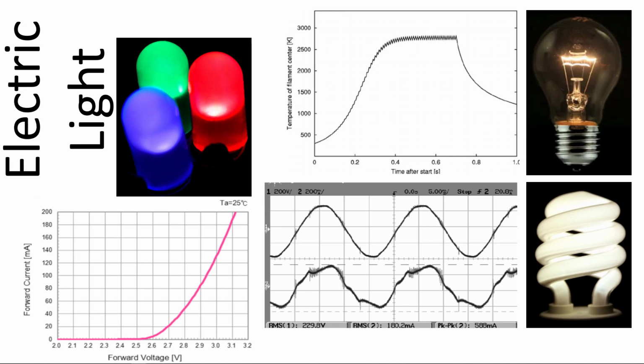LED lighting, and here I'm just showing a standard forward current with forward voltage. Notice that you have no real current until you hit about 2.4 or so volts. And as you steadily increase the voltage, you get steadily more current. With an LED, if you increase the luminosity, the output, up to a certain point, we'll say 100 milliamps of forward current, and you leave it there, then the curve flexes over to horizontal, and it stays steady state. There's no fluctuation whatsoever. So the adjustability, if you like, of the LEDs is much better than fluorescent or incandescent.